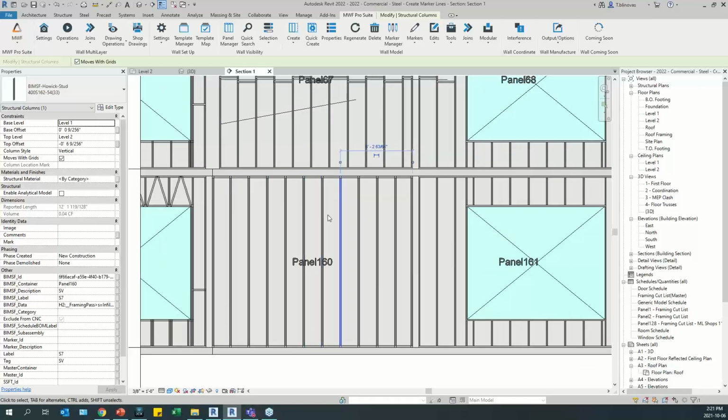So right now I do have some Howick families here, and we are going to add the marker lines. It's basically going to splice my studs and also my tracks, and it will add at the smaller pieces some R stud families that will slide in the main tracks and studs. So this will allow the panel to be smaller for transportation, and then it can be expanded to a custom size when it goes to the final location.